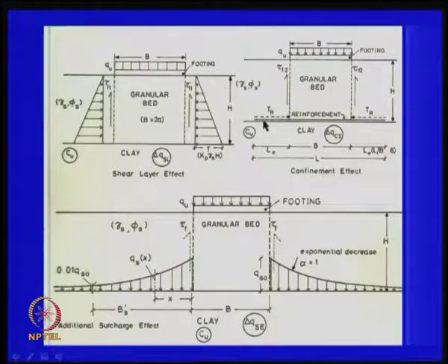Now, since you placed a reinforcement here, for example, a plate as a reinforcement, what is it doing? You already have this effect, which is because of the shear layer effect. The second thing is what is called the confinement effect. It is providing confinement; reinforcement acts in the opposite direction, right. As we just discussed, there is friction; the moment there is a tendency to move like this, there is a resistance here.